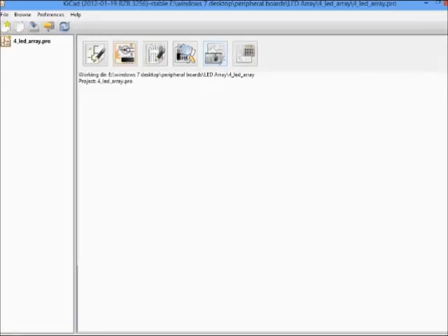So if you need to put logos on your PCBs, we can use this. And then this is a PCB calculator. Here you can calculate the track width and a whole lot of other parameters. But since the task at hand is very simple, it's just a 4 LED breakout board, we'll start out with the schematic drawing.